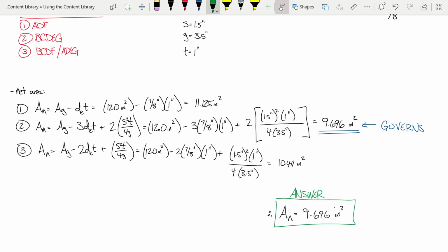Because here's the thing. Let's say I take that 1.5 inches and I make it 4 inches. Well, that's taking a connection that's this big, making it this big. And now I have to make the plate that it's connecting to that big as well, right? So where's the trade-off on what's more expensive, you know what I mean? So it's not that simple. I can't give you a definitive, well, just up it. You have to look at the loads, look at your connection scenario, look at your project constraints, and lay it out to get the best bang for your buck. So this is just another tool in your belt. So make sense?